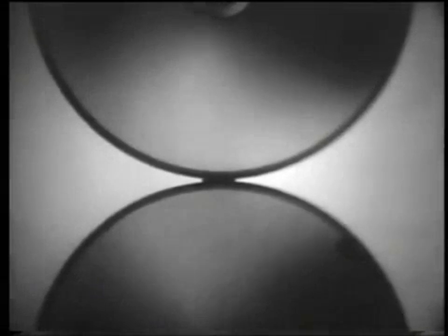When oil penetrates into a crack on a lagging surface under pressure, the crack closes. High oil pressure bursts the crack walls. So the fatigue crack develops into a pit. On the leading surface, the inner end of the crack first enters the pressure zone. In this case, the oil is squeezed out and the crack does not grow. Since the lagging surfaces are the tooth roots, they are pitted first.